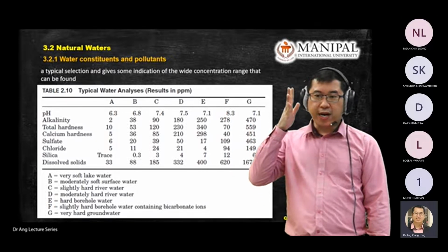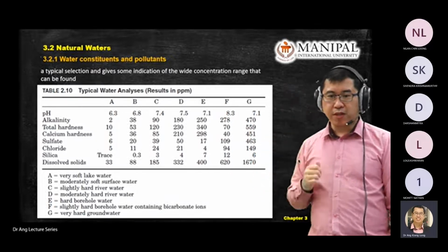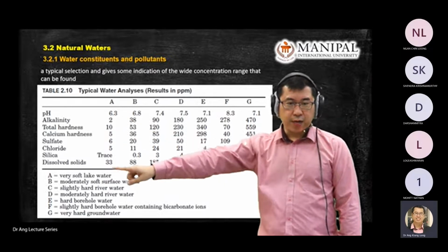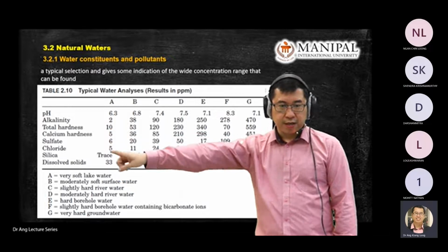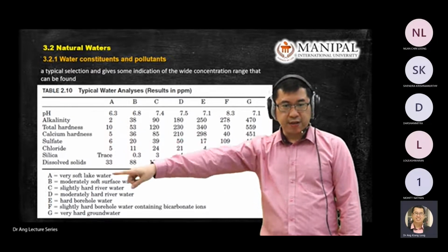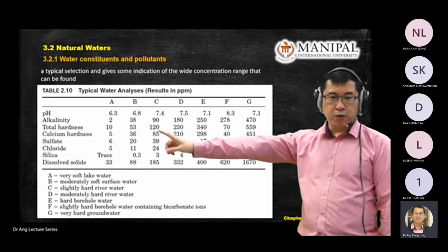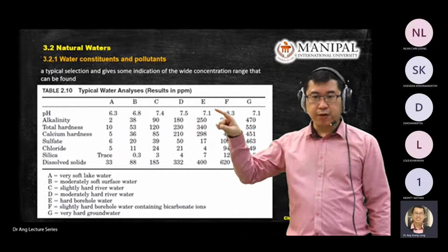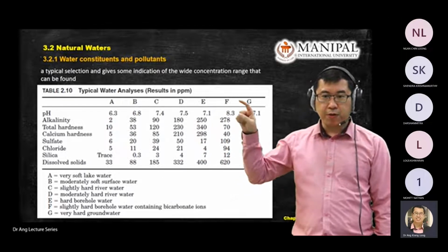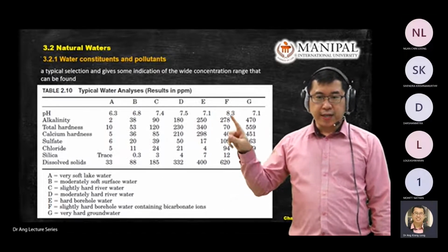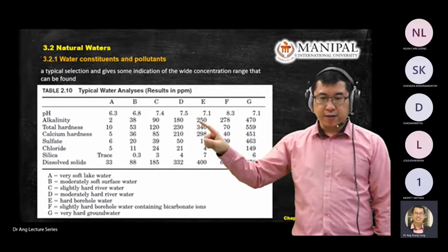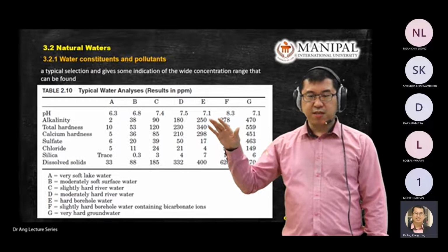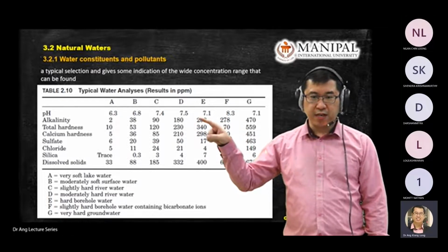But if you want to further identify what type of water you have, you look for a second parameter. It can be any one of these seven factors here. For example, you test for alkalinity. If the first row in your report gives you 7.1 pH, you have two possibilities, so you go and test another factor. Say the alkalinity value is 300.